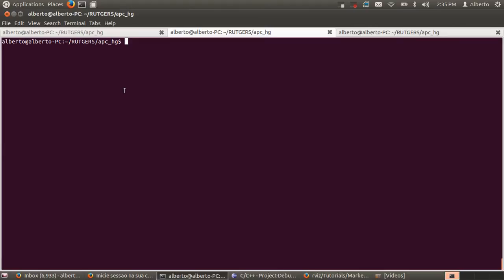After you have everything compiled, you're going to need to run this to set up ROS in that directory, and then run this ROS launch that runs mapping, object detection, and also localization. Localization currently is made by the mapping system. So the mapping system is going to do mapping and localization as well. And you have a second system for object detection. In this launch, we're going to launch everything.